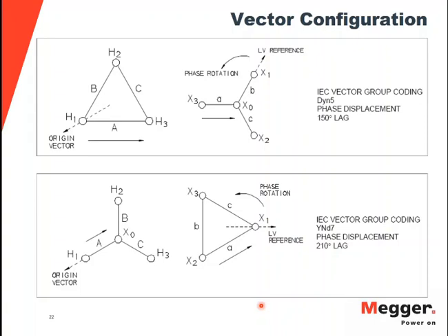If we have a transformer with an inductive LTC, do you recommend to make winding resistance in all the taps? For a transformer with an inductive LTC, actually it's interesting to do the test one direction and the opposite direction. So I would suggest you to go all the windings, all the tap change positions, and back and forth.